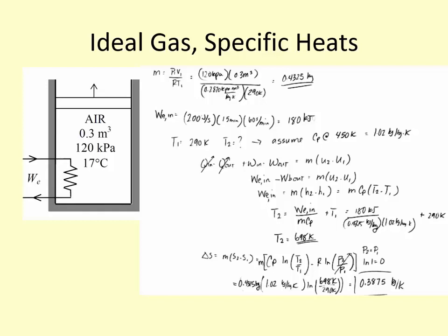So if we look at the tables, table A1, I think, for C sub P, let's see, for air, table A2B, our current temperature is 290 Kelvin, which is pretty close to 300 Kelvin. So C sub P is 1.005. And then it just continues to increase from there. Up to 450 Kelvin is 1.02. Up to 800 Kelvin is 1.099. So we have to make an approximation.